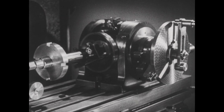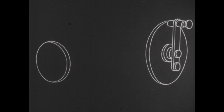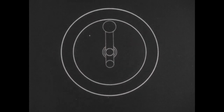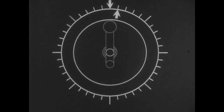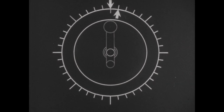The operating principles of the dividing head can be further simplified by imagining the hand crank to be centered directly in front of the work. If 40 equally spaced cuts were wanted, each full turn of the crank would move the work 1/40th of a complete revolution, thus locating each of the 40 cuts.